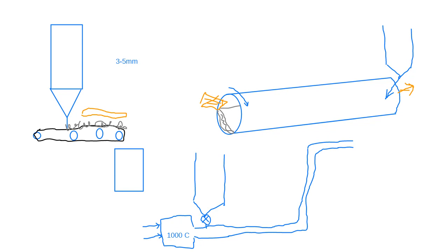And as they're pneumatically carried, of course, you'll get flash heating of the particles by this very hot gas, a very good heat transfer, and therefore the particles will dry in the really small amount of time that it takes for them to move along here, and then eventually into, oops, I've got the text tool on instead of the pencil tool. And the pencil tool is to show a cyclone. I'm going to show a cyclone like this. Oh, that's an ellipse.